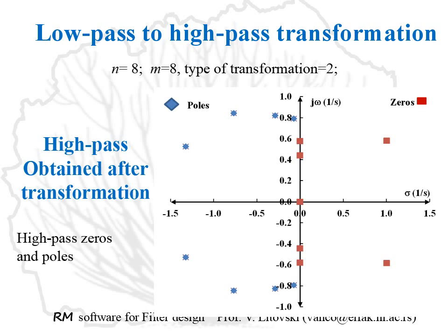Here is the result of the mapping. As can be seen, the poles and zeros are now separated. Half of them are in the top part and the other half in the bottom part, and shifted toward the edge of the bandwidth, and of course zeros in the origin are created.